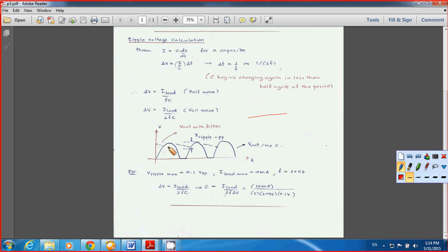To get very close to a straight line as the DC voltage, you need to connect, just like I mentioned before, your R and C, or low pass filter circuit, right after your full wave rectifier circuit.